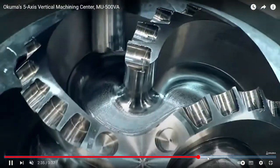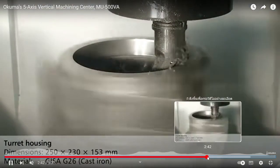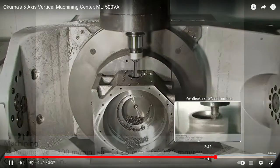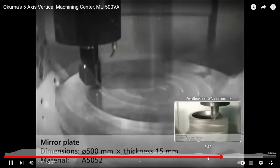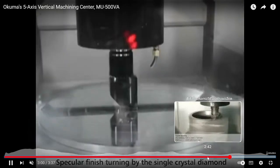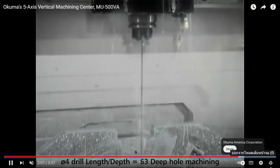The table flips up and the cutting tool moves around the flat surface, because a three-axis machine cannot move the table around the y-axis and x-axis, and a 5-axis can. It means the undercut area will move up and the cutting tool cuts around that area. This is the limitation of the 3-axis machine, right?